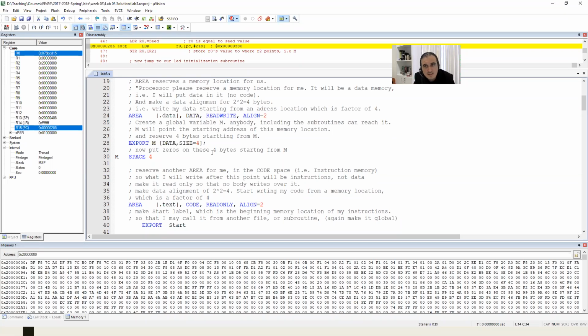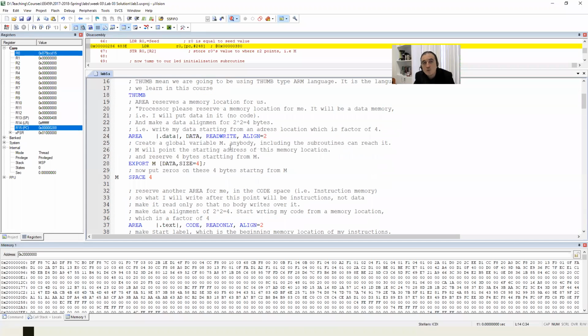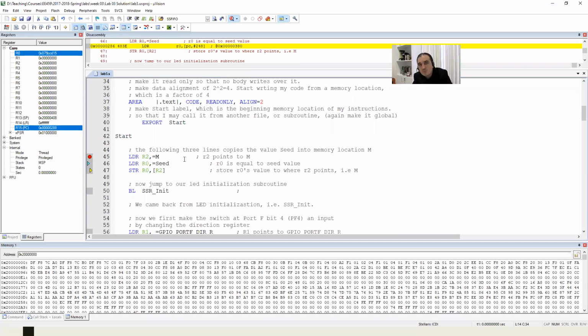There's define and there's also const, which stands for constant. So if you want to define a constant, use EQ. So if you see code in Keil like this, definitely somewhere in your code somebody has defined these. You don't know where, you cannot find it in the code.